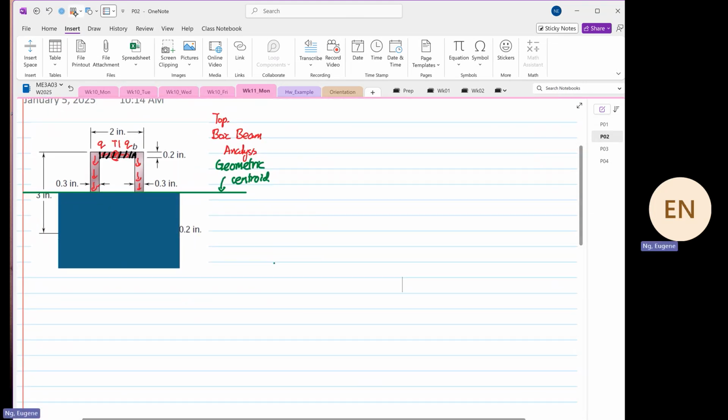So we're going to find the shear stress at point B. And this will be equal to Vy over Izz times Qz over t. So at point B, I hope you all write this down. Very, very important.